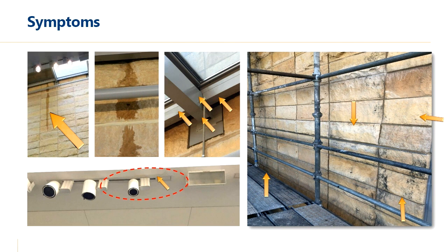During our initial project, we were walking the site and we commented on how significant some of the exterior conditions were with regard to efflorescence or white staining, some organic growth or the black staining, and what looked to be some scaling or spalling of the masonry elements. And they said, yeah, it gets dirty quite often. We're cleaning the wall every 4 to 6 months, which is a pretty aggressive schedule for cleaning.